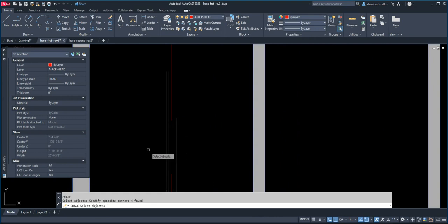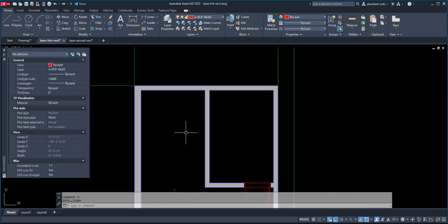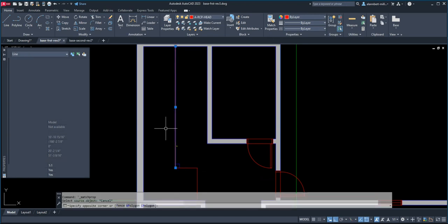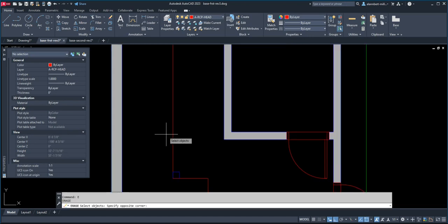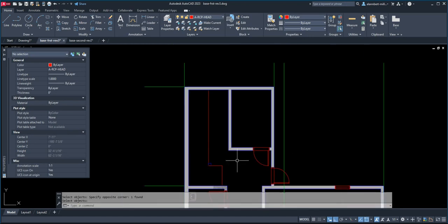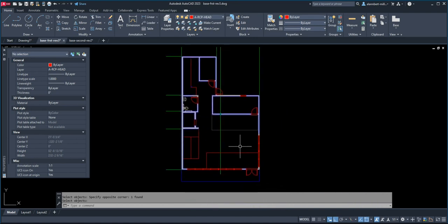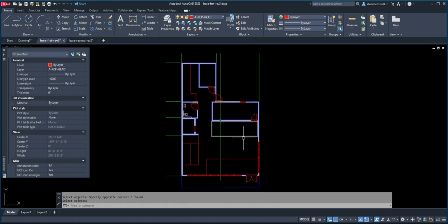Then erase these and let's just do this and select that and do a perpendicular because it's just one line. Oh, what's going on? There you go. And then we're going to make sure that this and these two are on layer RCP head. There you go. Okay, there's something here. So that's what we're going to see above is an opening or the edge of the floor. And basically, that's our base plan, and we're going to be ready to do the ceiling. We're going to leave that here and fix it later, but we're going to do the ceiling next.